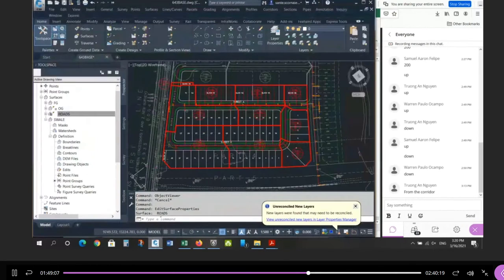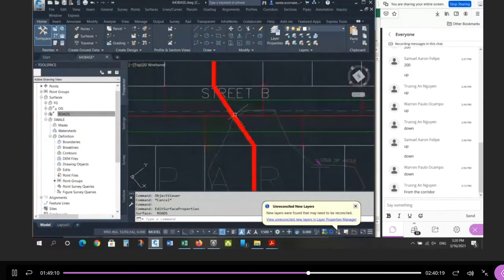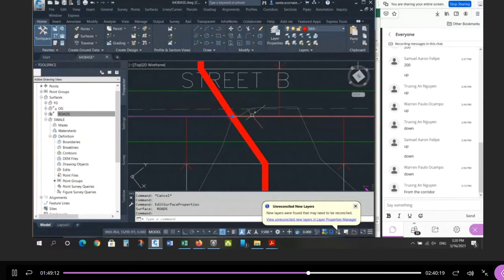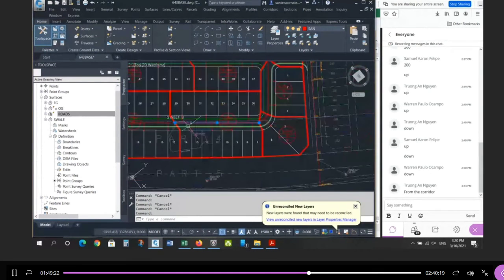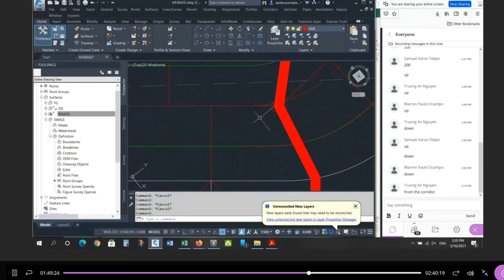We're going downhill. We're going to start here. We're going to go to here. The difference in the pipe size, that's one number. Straight through, that's another number. Whichever one is bigger, that's what you subtract from this invert to get this invert. And then you go downhill, right? 0.5% based on the length.